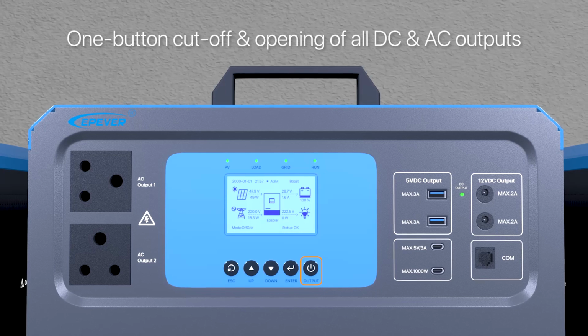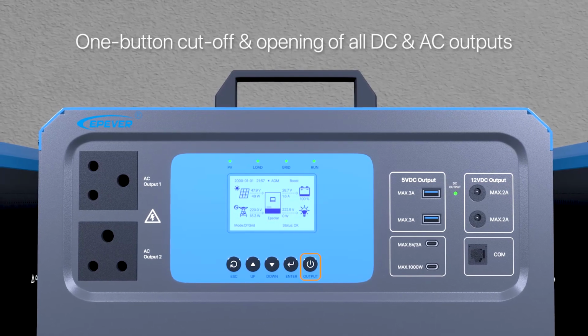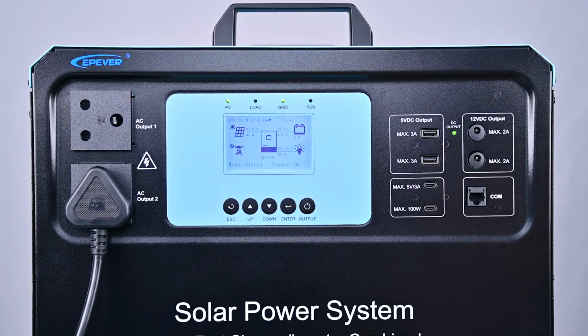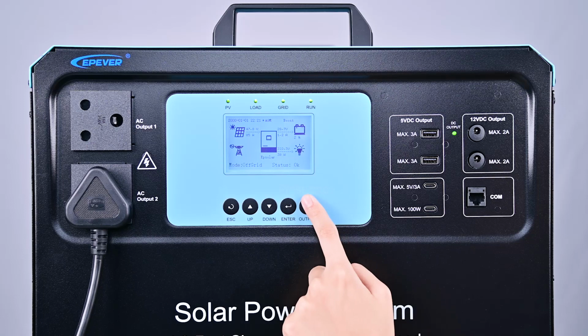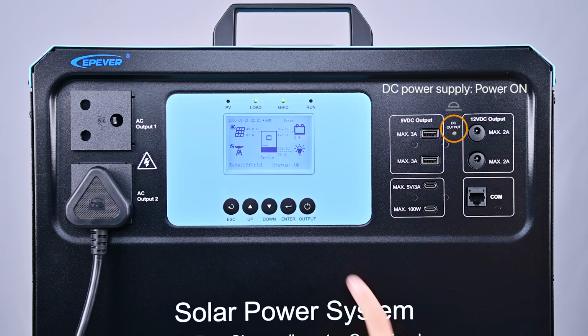The Output button provides a quick one-button cutoff and opening of all DC and AC outputs. To cut off all DC power supply, simply press the Output button once. Then we can see that the DC output LED light on the right side goes off. It indicates that the DC power supply has been cut off. To re-engage the DC output, just press the button again.